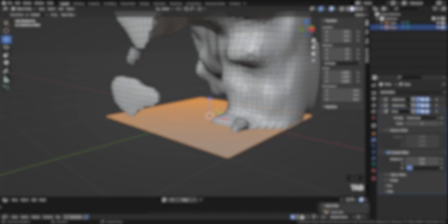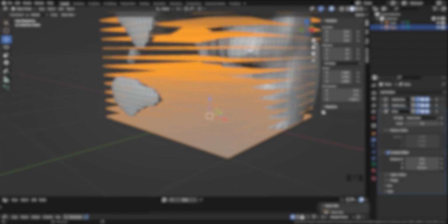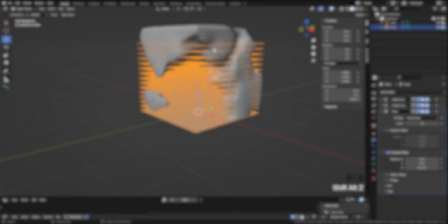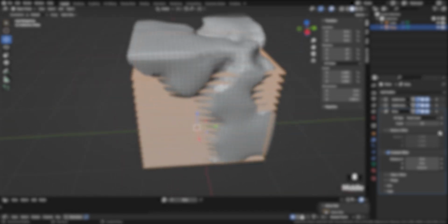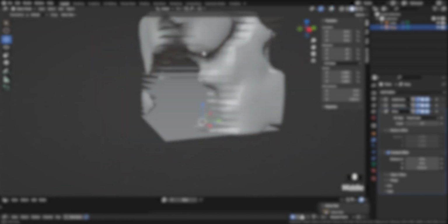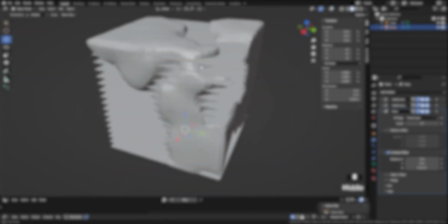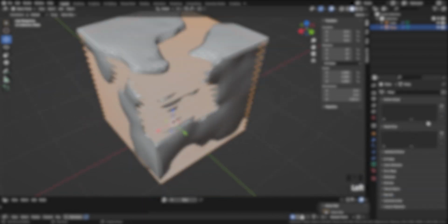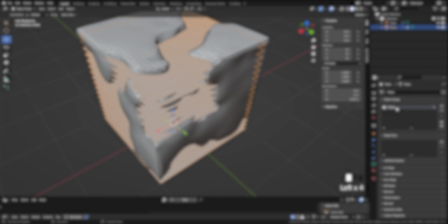Before we go further, I want to explain the method we are using. You can probably guess that we want to subtract the mesh we made in geometry node from the plane that we just made. But boolean is not the right way because you can't use boolean for animation well. Boolean is not that accurate. So we use another method, which is dynamic paint.